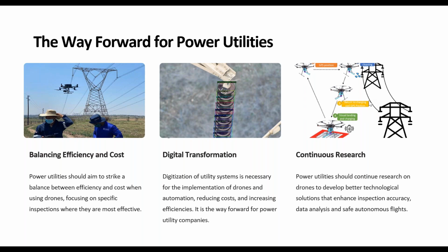There are a number of sensors that need to be used to ensure that a drone can pick up and keep a certain distance to this line, follow the line path, sag with it, and keep adjusting the camera accordingly. And this inspection will be video based, where we will have an IR video, visual video, and if we have a UV camera there, a camera recording corona activities.